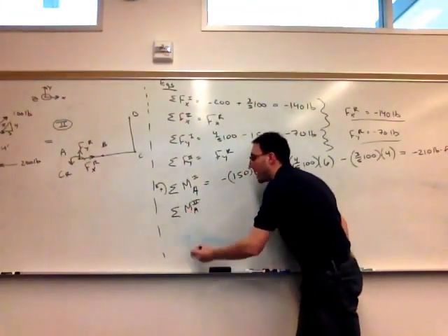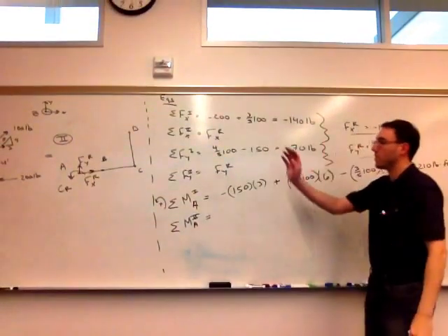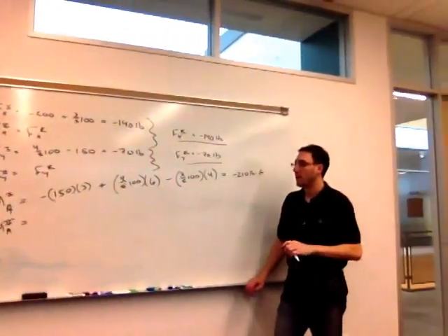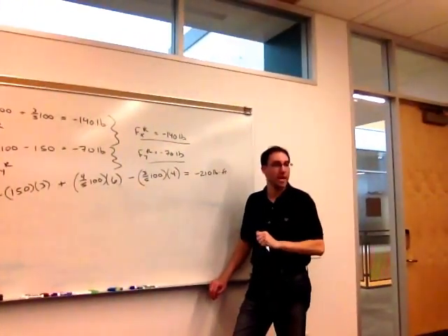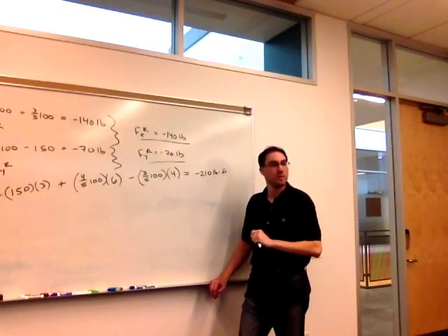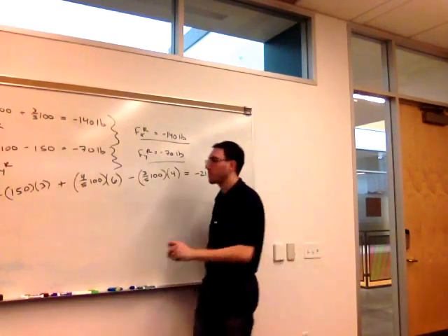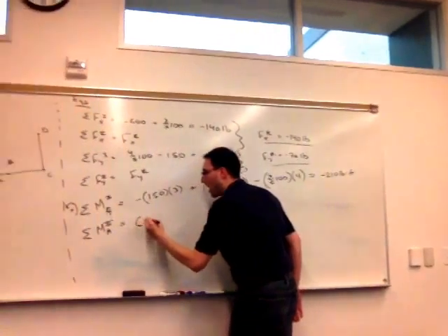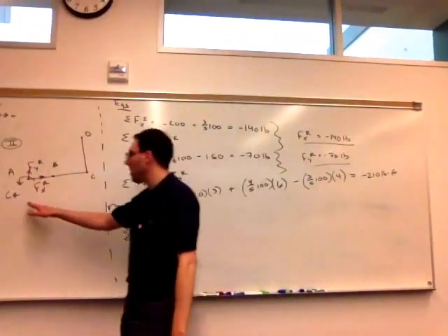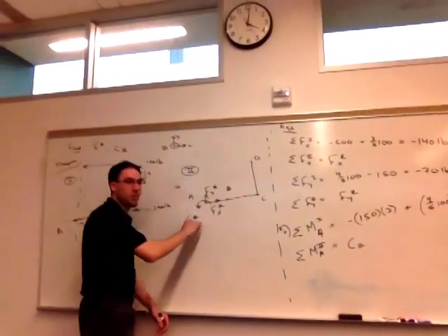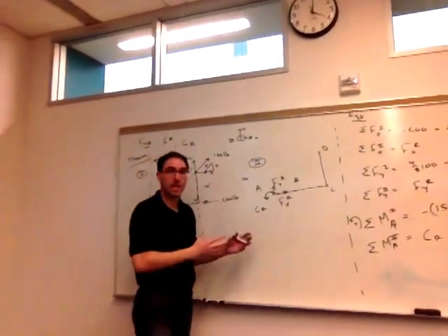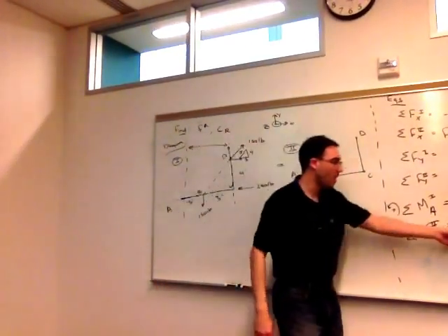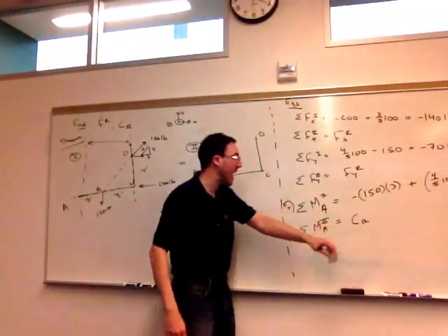So I have to choose A in system 2. So looking just at that picture, what is the sum of moments around point A going to be in picture 2? Right, CR, I assumed CR was positive. And remember, couples contribute to the moment no matter where they are and the same amount. So it's just CR. I don't multiply it by any distance ever.